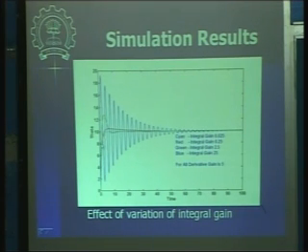So you can observe clearly here that the steady state error is taken care of. You are reaching the final position. But when you increase the gain values by an order of magnitude, then you see that your response becomes oscillatory in nature, and again the settling time goes on increasing. The time it requires to reach the fixed final position goes on increasing.